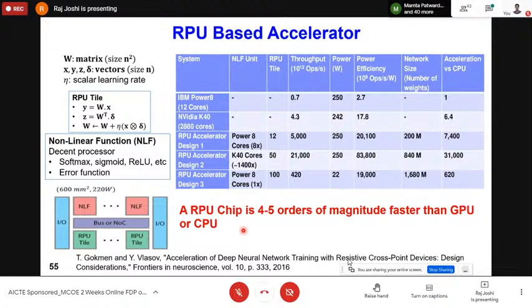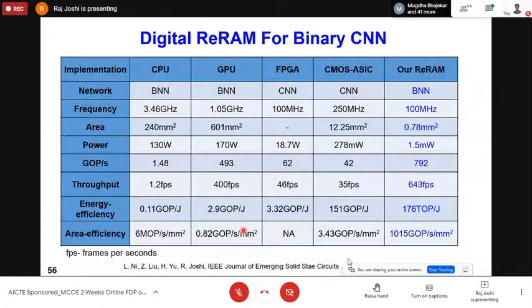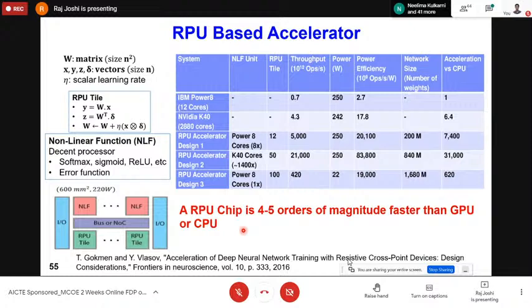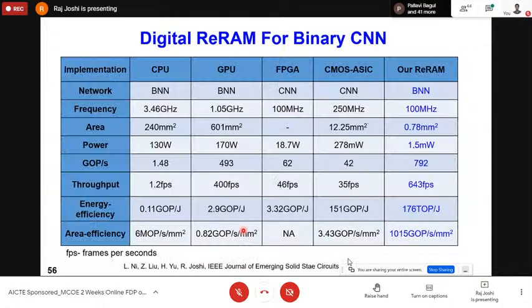But based on that, one can also come up with what are called capacitive processing units by using capacitors. This is the resistance, right? Resistive memory. So similarly, there are ideas which can go beyond that as well. This is all about analog, which I talked about, right? All these non-volatile memories can store these discrete values by applying one voltage on one side and another voltage on the back side, and based on the delta of that voltage, a corresponding resistance will be stored in that memory.